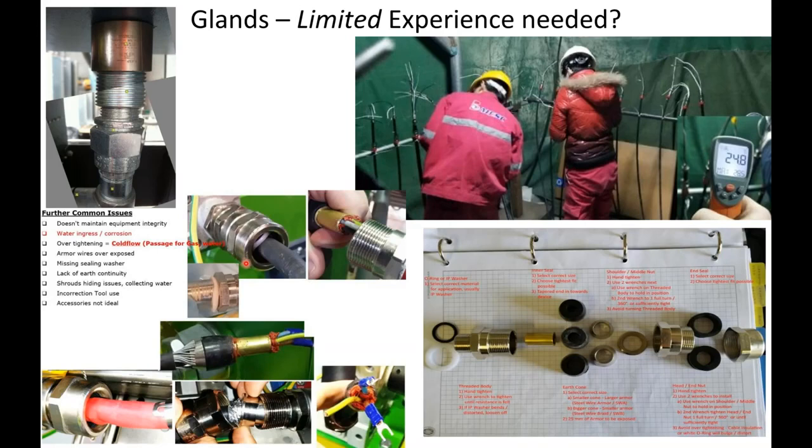Now, the other problem is that people will assume they buy a certain type of gland and they're wonderful. What about the cable? If the cable is of poor quality, this one here is bulging, there's no possibility to install the cable gland correctly. So these poor gentlemen and ladies will struggle every single time, and it is not their fault.